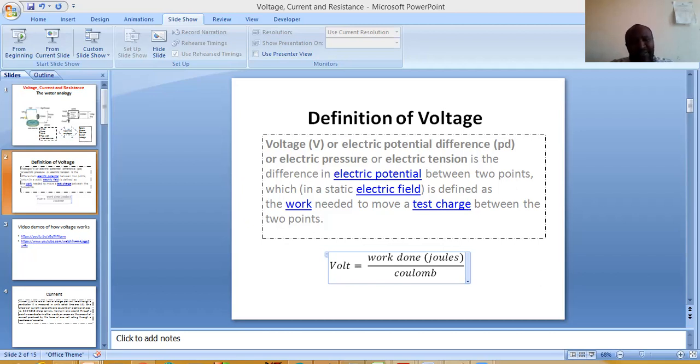And in electrical or electronic circuits, we very often make use of resistors. But one thing you have to be keen about is the power rating of the resistor. Because if you happen to dissipate more power than the rating of that resistor, the device will go into smoke.